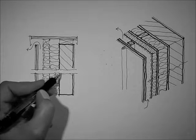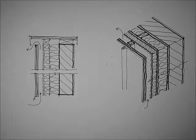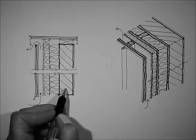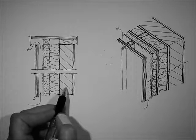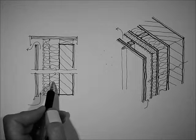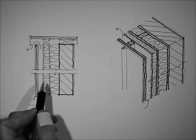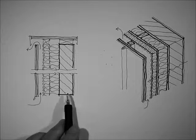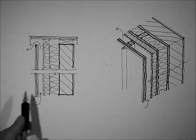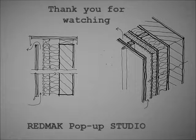So that is one example of a wall that conforms to the ideals of the first film. Lots of masonry on the inside creating a high thermal mass building, insulation near the external side of the envelope, and decreasing vapour resistance to the materials until we get to this one, which is why we've got ventilation in behind it.